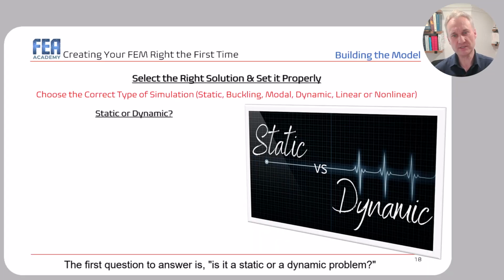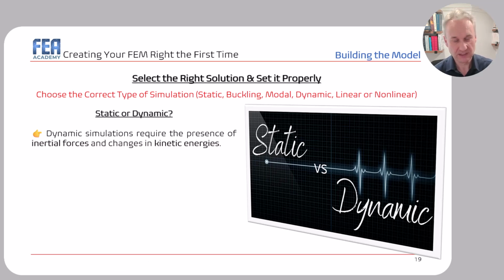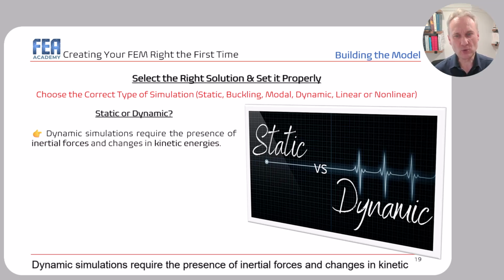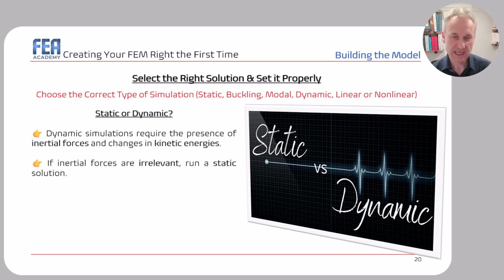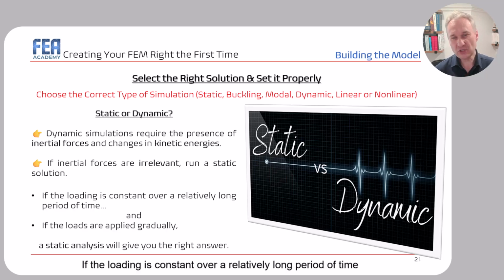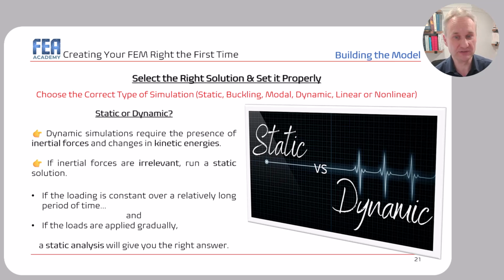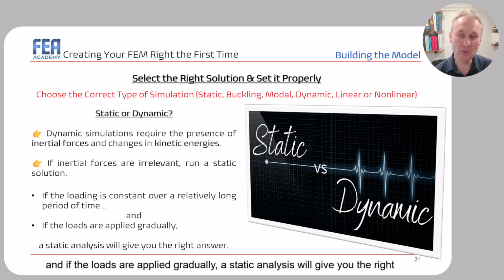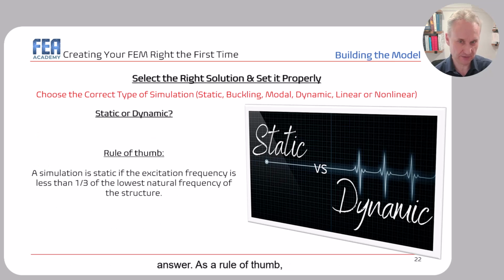The first question to answer is: is it a static or a dynamic problem? Dynamic simulations require the presence of inertial forces and changes in kinetic energies. If inertial forces are irrelevant, run a static solution. If the loading is constant over a relatively long period of time, and if the loads are applied gradually, a static analysis will give you the right answer.